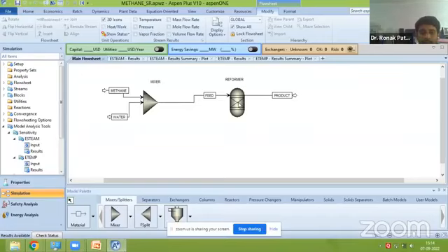And here I want to explain the effect of a parameter, like the steam reforming that is taking place in the range of 400 to 900 degrees centigrade. Every time you would need to go to the reformer, change the temperature to 400 and see what the product composition is. Then again you change the temperature from 400 to 410 degrees centigrade and observe the product composition. So here I am going to explain the importance of a sensitivity analysis. Sensitivity analysis is going to give you the effect.